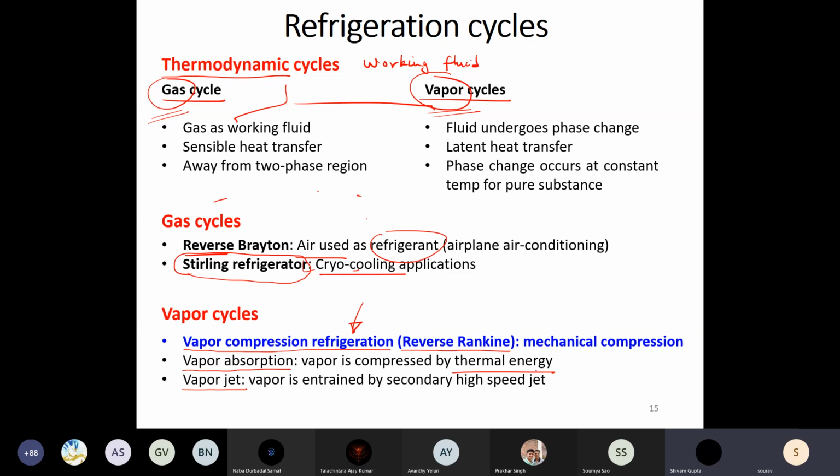You provide heating and cooling in certain chambers, and you can reverse the directionality of the flow of the working fluid. People started off with sulfuric acid and water, and then they moved to water-ammonia cycles and water-lithium bromide salt cycles. A few cycles are right now available, and there are commercial products based on them.